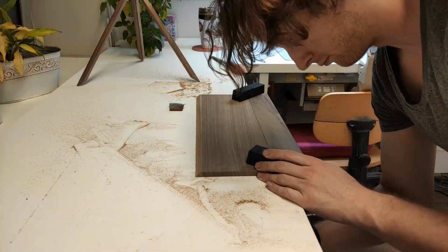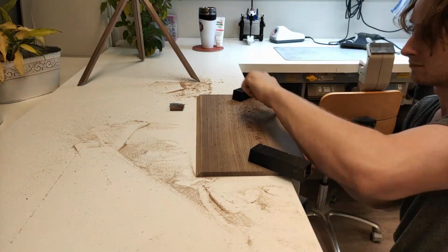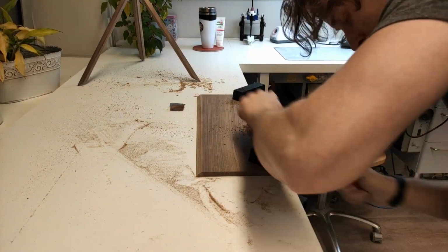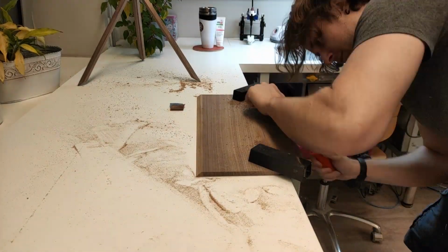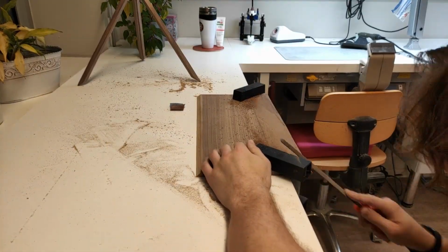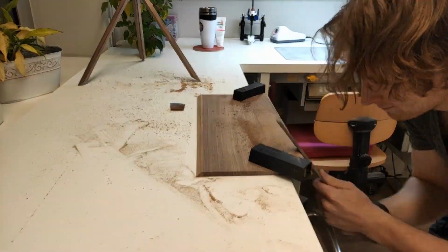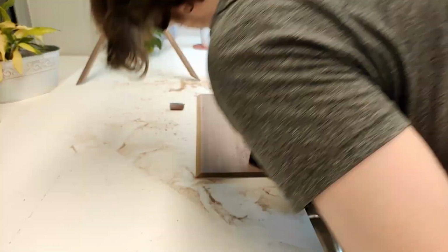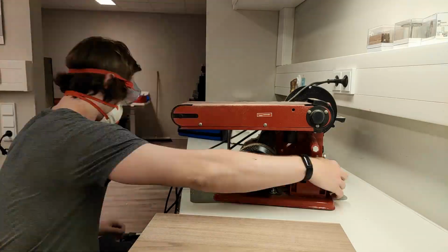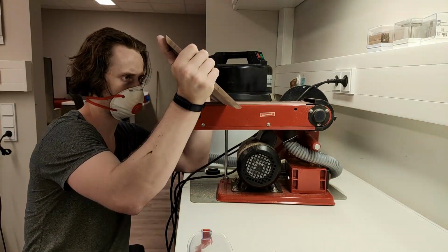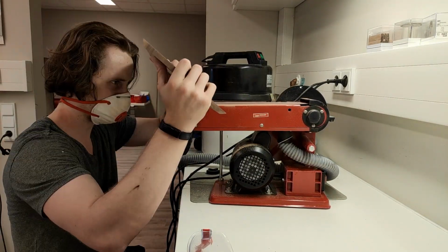One of the things that I really wanted to have with this box was a seamless edge, and this was kind of a problem because I already said that I don't have a table saw. And without a table saw, it's much more difficult to get a nice 45-degree angle into the wood. So what I decided to do was basically the same thing that I did with the tetrahedron build, where I just needed to file away a lot of the wood by hand and then use my belt grinder to really get this nice smooth 45-degree angle in there.